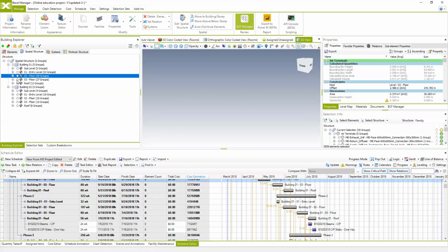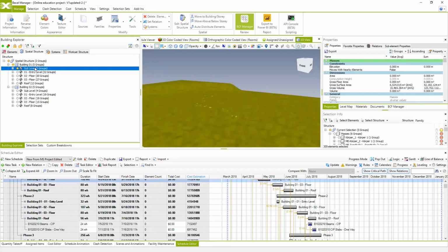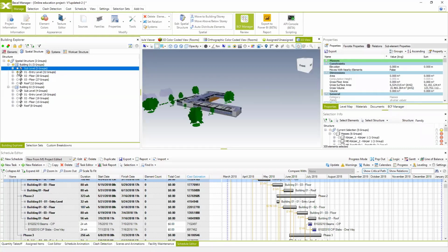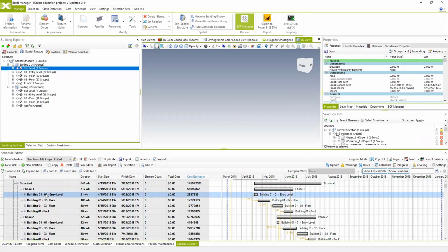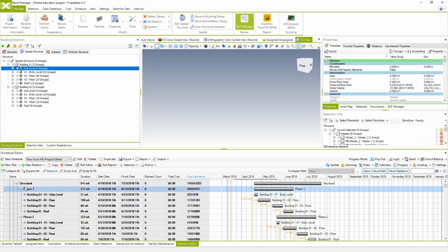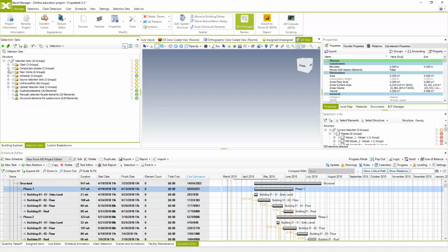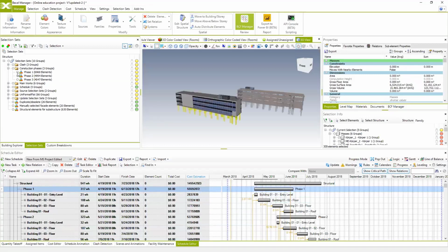So you have automatic segregation based on the stories and the buildings, and you can use this already created segregation of the elements to link them with the hierarchy levels of your schedule, to link it to the specific BIM model, to the story of the schedule. And of course, the next hierarchy level is in this case phases.